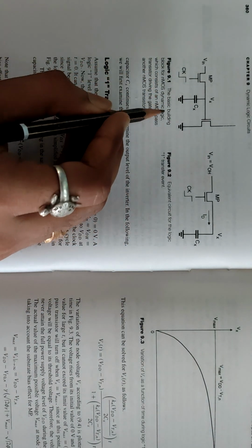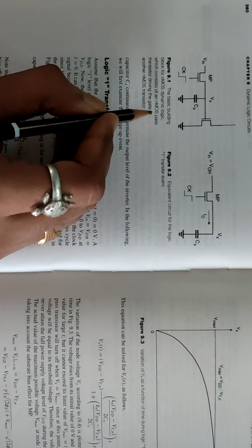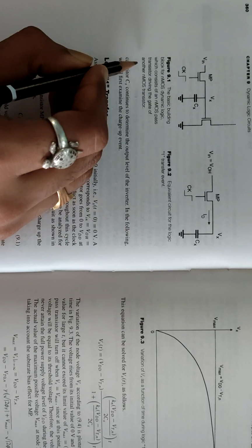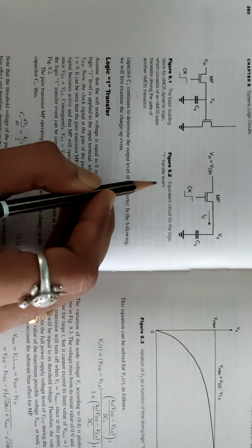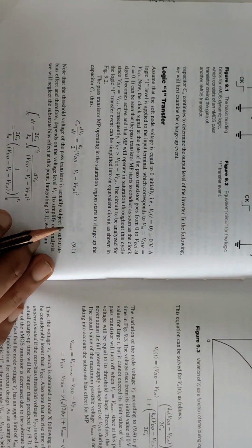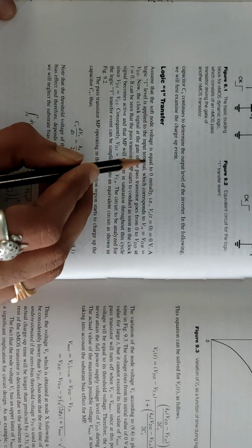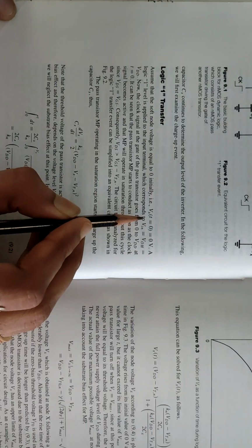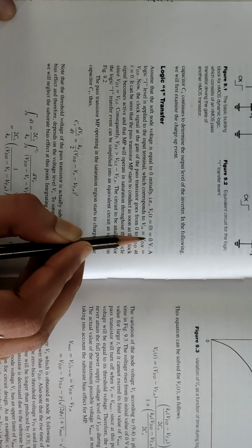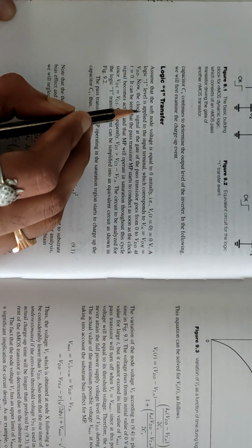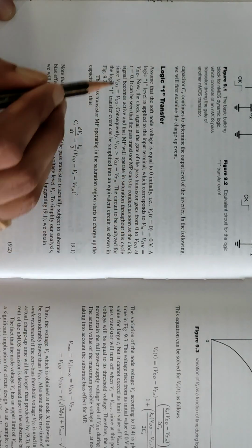As you can see in the figure, the basic building block for NMOS dynamic logic consists of an NMOS pass transistor driving the gate of another NMOS transistor. Equivalent circuit for the logic 1 transfer event. Logic 1 transfer: assume that the soft node voltage is equal to 0 initially, that is Vx(t=0) = 0 volts. A logic 1 level is applied to the input terminal, which corresponds to Vin = VOH = VDD.